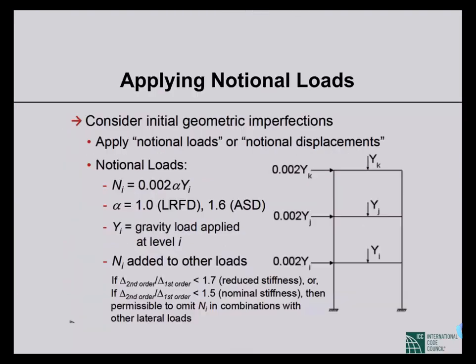So how to apply the notional loads? These notional loads are actually to consider initial geometric imperfection. And the notional loads can be applied as loads or notional displacement. Usually we apply them as notional loads. Here you see the factor for LRFD is 1, and for ASD, the factor is 1.6. And the last thing is very important.